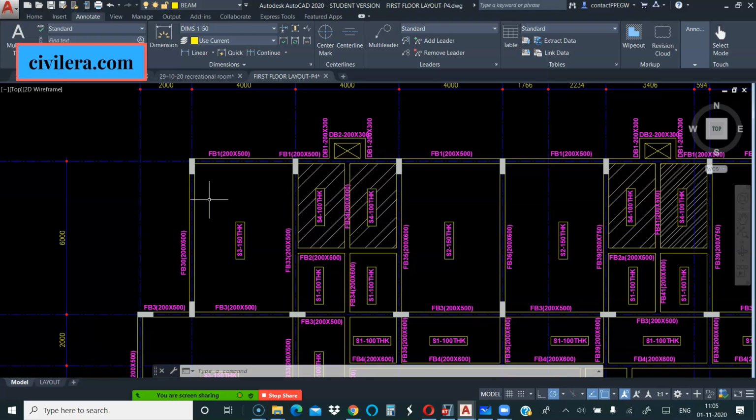But many times you might have heard clients and architects saying that reduce the number of columns, it will be more economic. It's not like that. If you reduce the number of columns, there is no guarantee that your structure is going to be economic. Many times it will become uneconomic because your footing size increases. If you are designing for seismic, your seismic demand has to be met by less number of columns. So maybe you need a larger shear wall, or sometimes your column size will shoot up. So it's not right to say that less number of columns are going to be more economic.